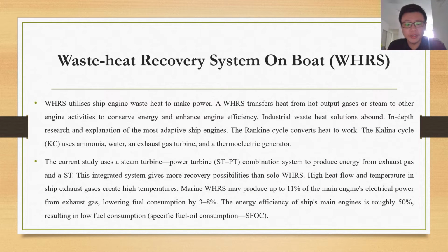A waste heat recovery system, WHRS, is a system that uses waste heat from the ship engine to create electricity. A WHRS transfers heat from sources such as hot output gases or steam to other engine operations to save energy and improve the energy efficiency of the ship's engine. Many waste heat technology solutions are available for industrial applications, with in-depth analysis of the most applicable options for ship engines, along with a complete description of these technologies.